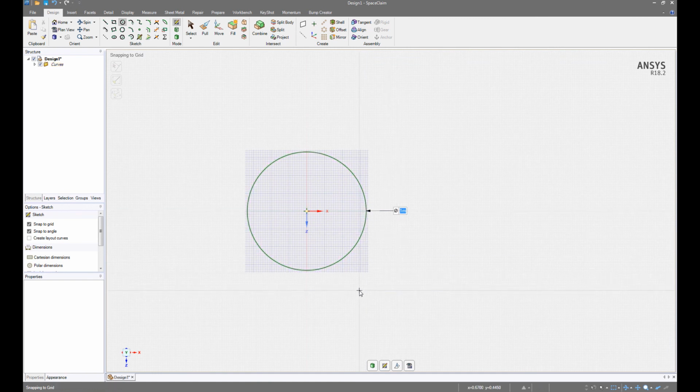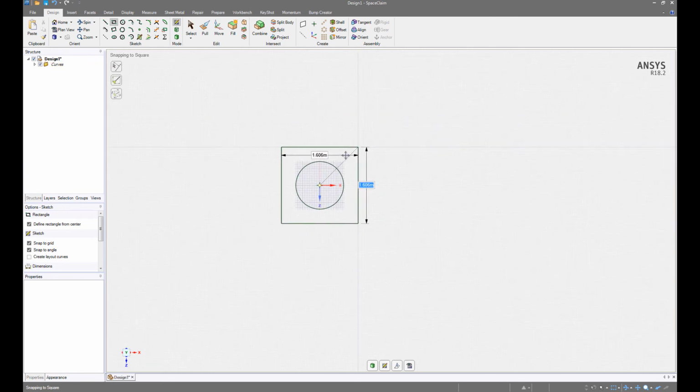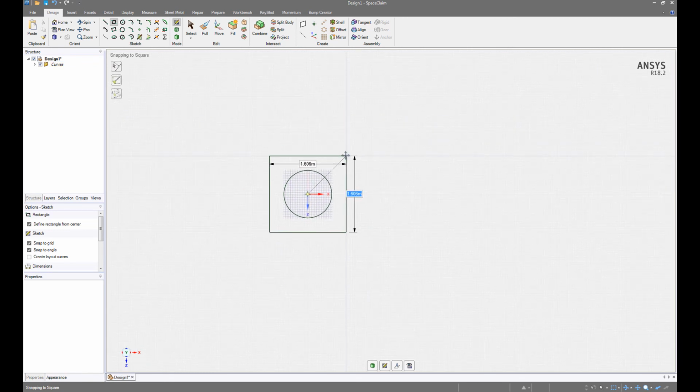The nice thing about flow over a cylinder is that it's well tested, well understood, and there's actually a lot of interesting phenomena that goes on in the cylinder flow that may be challenging to model unless you have the proper setup. So here we go. We're going to start by defining the geometry. I'm in the ANSYS SpaceClaim system.